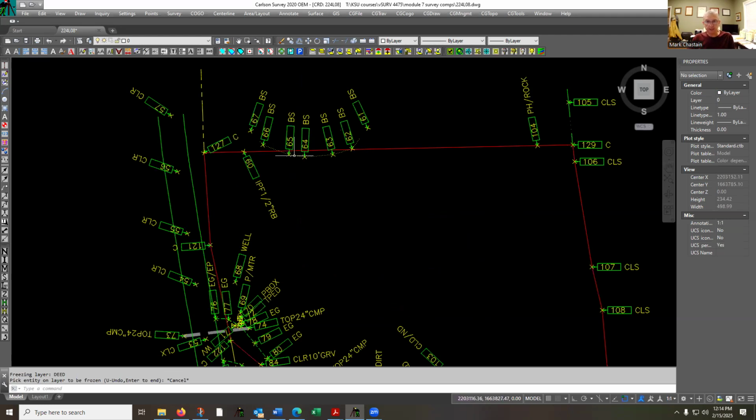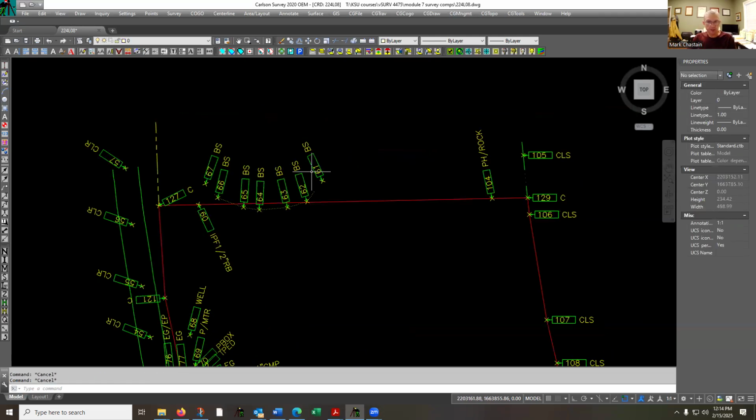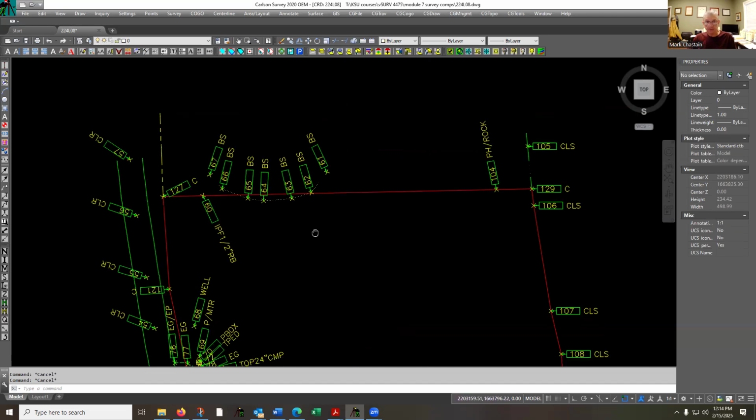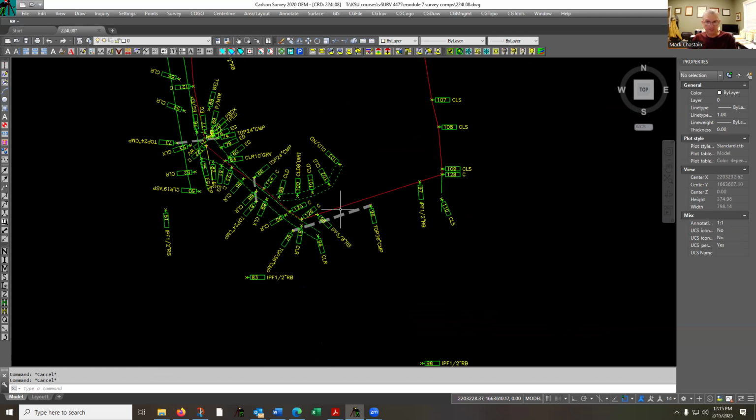So we found the base of a slope. The neighboring lot built, again, this is mountainous property. So when they built their house, their fill slope extended down into our property. So that's some possession, some adverse possession, occupation at one time. Is it an encroachment? We don't really know. That's really not our job as surveyors to classify it, just to let people know what's out there.